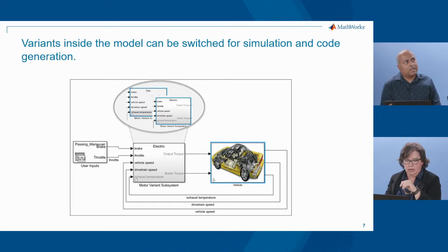Yeah. So the one I can think of is, let's take the example of something called fan control. Maybe I'll just give a little bit of background, right? So this is on internal combustion engines. To ensure that the engine doesn't get too hot, you have sensors, and based on some thresholds being exceeded, you trigger the fan to be turned on to cool the engine and thereby cool the entire system down, right?